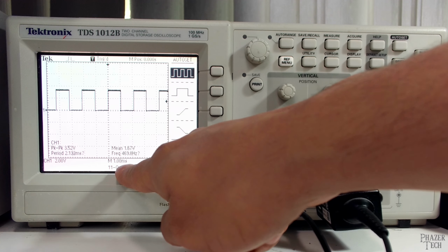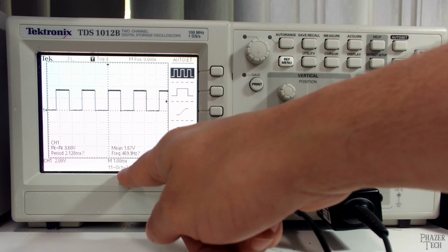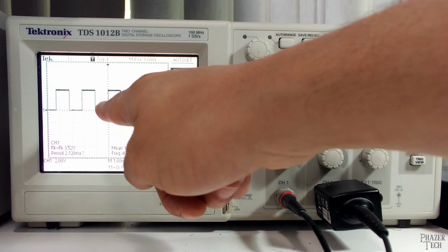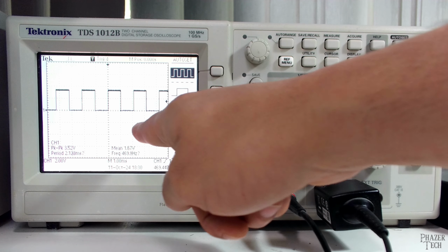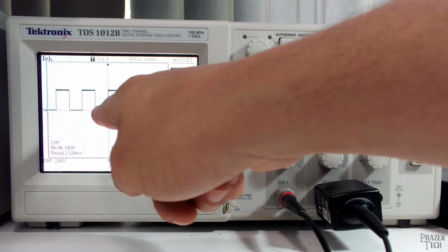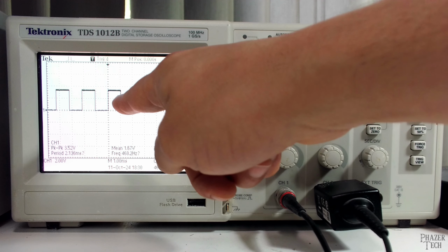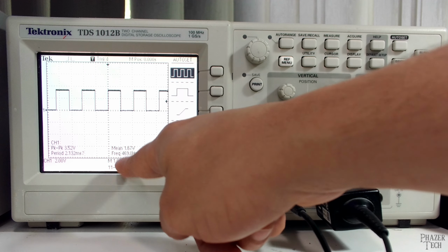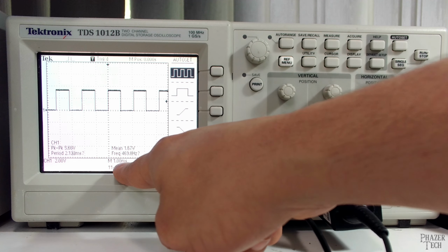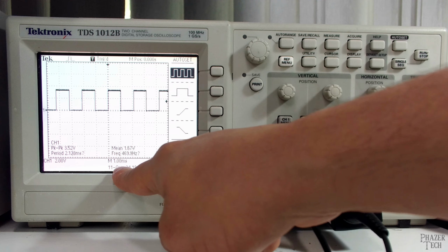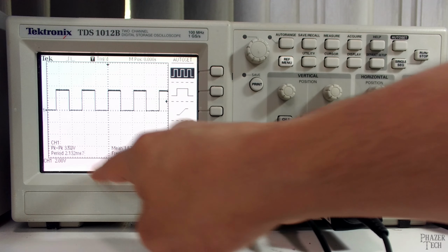So since this is in the unit of time or seconds, this tells you the value of each square on the x-axis. So if we go from the middle point to the end of the first square, this indicates 1 millisecond of time. Since that is what is being displayed here, that's what it's set at currently. And if we look at this channel 1, 2 volts, that's telling us the value of each square in the y-axis. So if we start from the middle and go up 1, that is 2 volts.